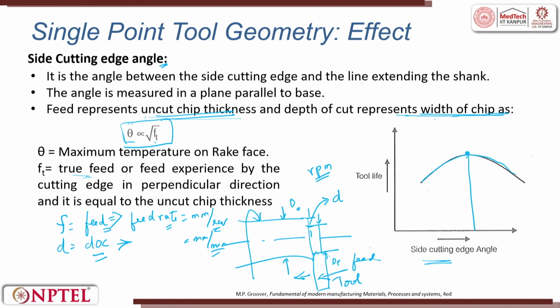So, the feed what we define here is the true feed, or the feed experienced by the cutting edge in the perpendicular direction, and it is equal to the uncut chip thickness. So, uncut chip thickness is there. We will see in detail what is chip thickness and uncut chip thickness as and when the lecture flows.